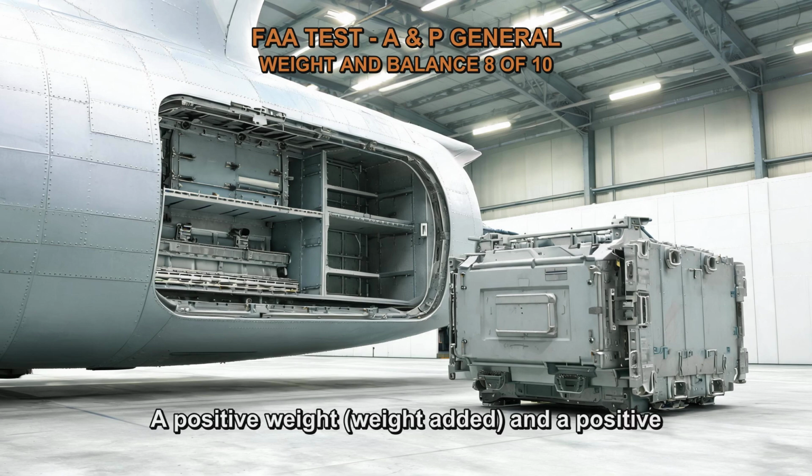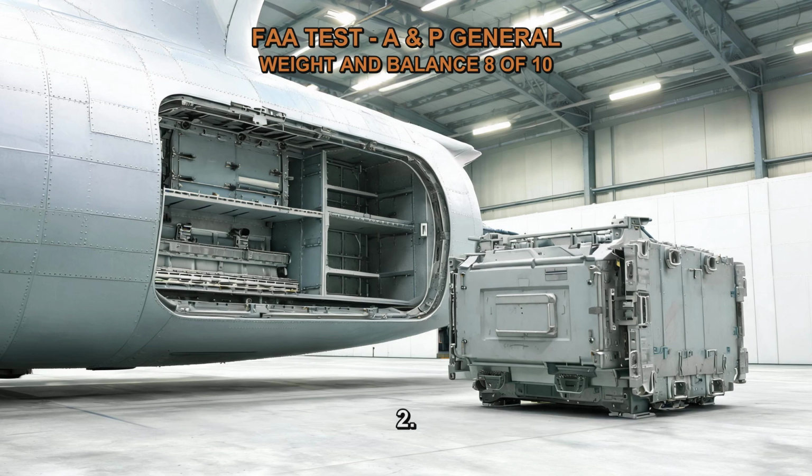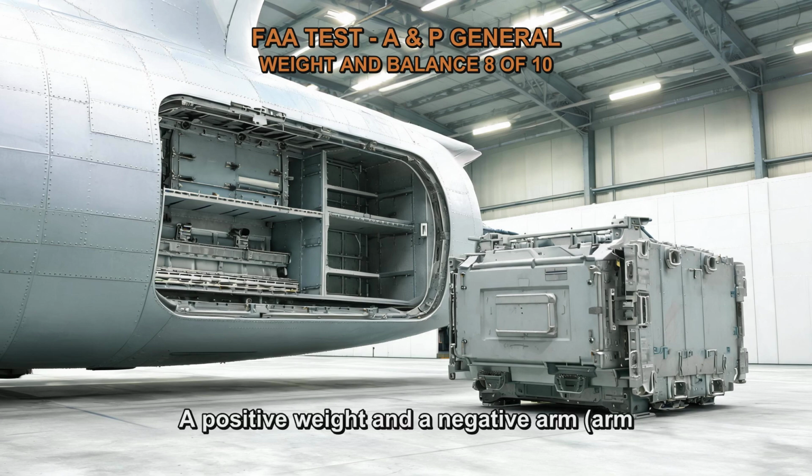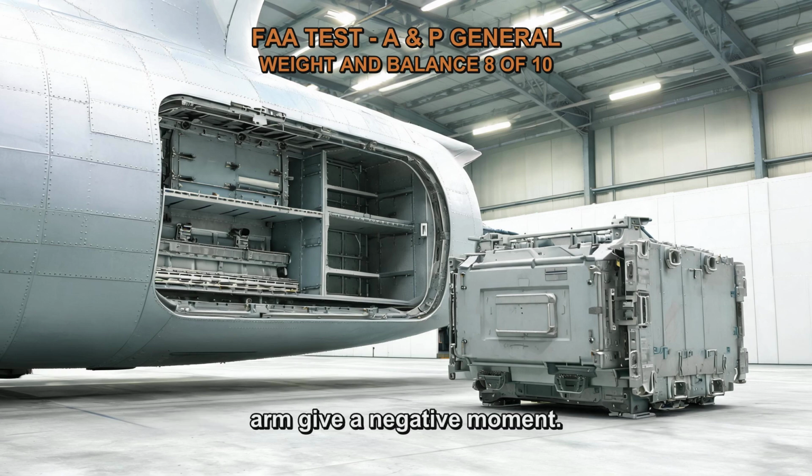1. A positive weight added, and a positive arm behind the datum, give a positive moment. 2. A positive weight and a negative arm, arm ahead of the datum, give a negative moment. 3. A negative weight, weight removed, and a positive arm give a negative moment. 4. A negative weight and a negative arm give a positive moment.